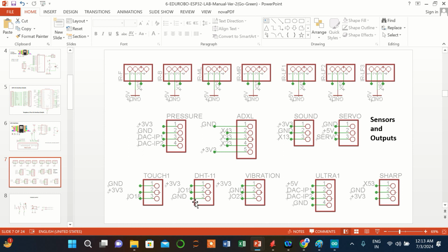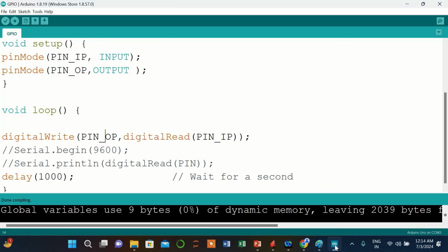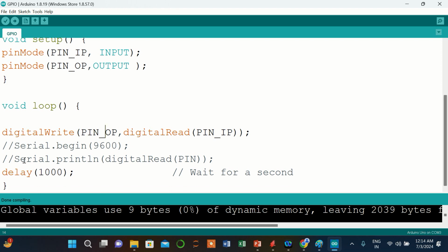So it is easy to use a 2-pin jumper. If you have a female to female or male to male connector, then probably you can use IO23, IO18, or the DAC output pins also. But carefully you have to give either VCC or ground looking at the pin configuration. You should try this using digitalRead and digitalWrite syntax for reading and writing the pins.